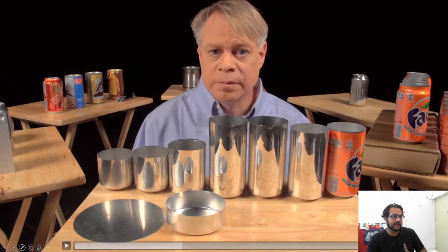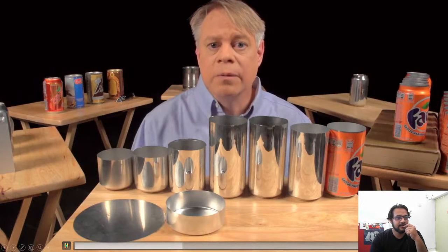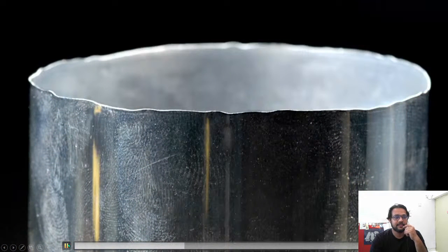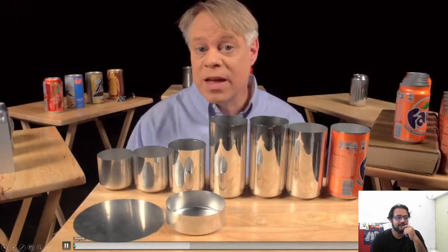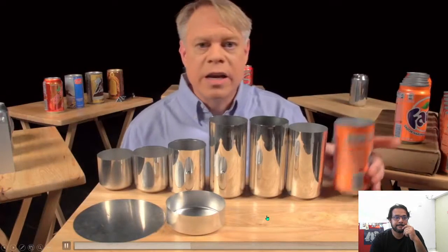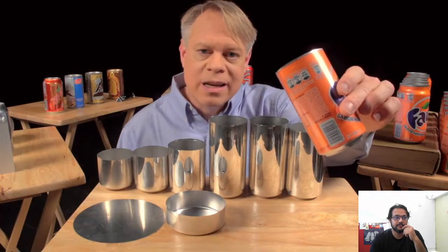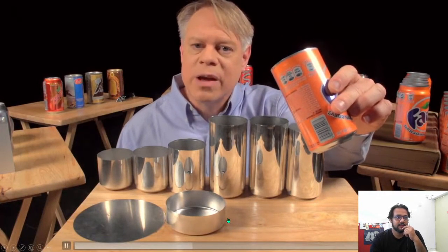Okay. So now, if you look closely at the top of the can body, you see that the edges are wavy and uneven. These irregularities occur during the forming. To get a nice, even edge, about 6 millimeters is trimmed off of the top. With an even top, the can can now be sealed. But before that sealing occurs, a colorful design is printed on the outside. The term of art in the industry is decoration.